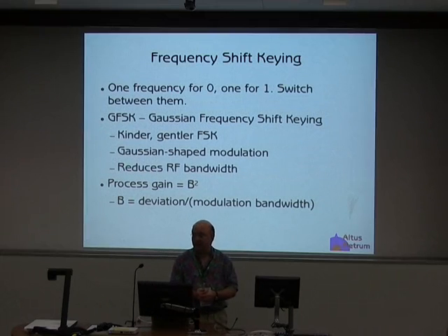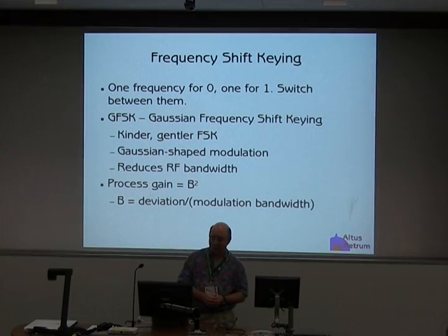Okay, frequency shift keying. Frequency shift keying, in the audio space, is known as frequency modulation or FM. It's a pretty common technique. Why are we using that? Well, we're using that because that's what our radio chips do, and that in fact is pretty much all you can get in common off-the-shelf radio chips. Trying to build a binary phase shift keying radio is really pretty hard because you can't just buy a binary phase shift keying transmitter without buying all the rest of the modulation stuff as well.